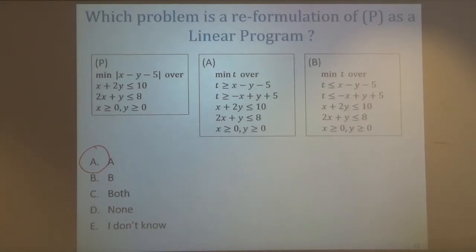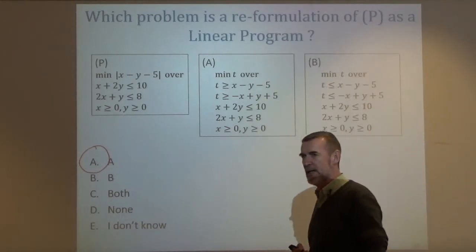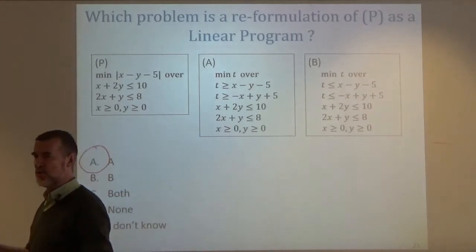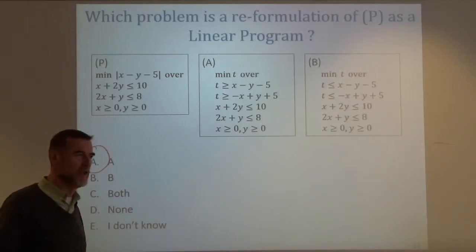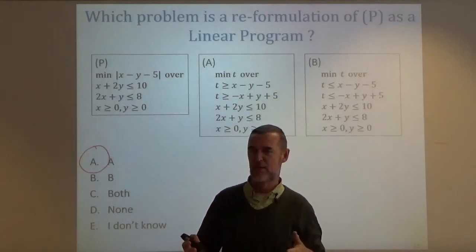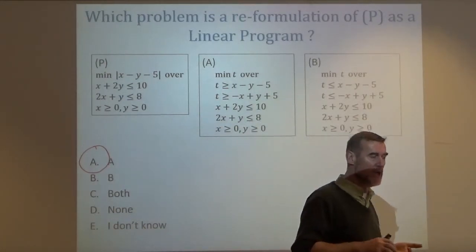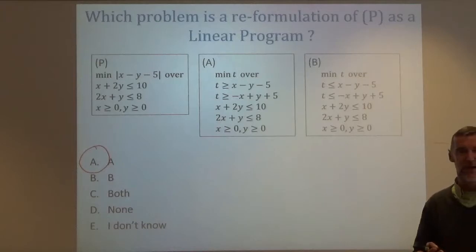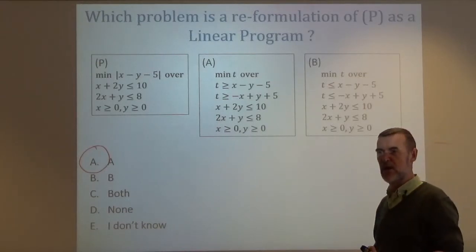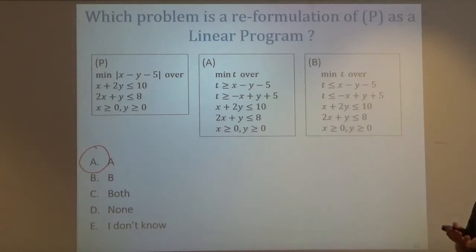That's quite a useful trick that we will use a lot, and that is used a lot in general, when we have to take costs, for example, that are a penalty function. For example, we want to run a grid with certain constraints on some values, but it's a soft constraint. We would like something to be not too large. One way to do it, which is very frequently used, is to take a penalty function, which is the square of the deviation that you have. But if you take the square, you will have something nonlinear. If you take the absolute value instead of the square, you will have something linear, which will greatly simplify your problem. So if you have the choice of the problem formulation, and very often that's the case.